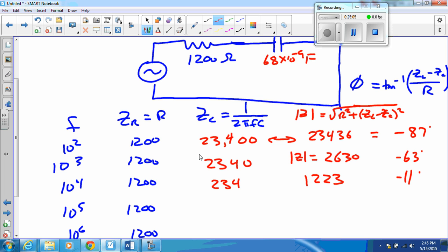Why does it do that? Because as we increase the frequency, the impedance of the capacitor goes down, down, down. And the impedance of the resistor doesn't change. Let's actually see that in the circuit over here. If I put this now on 10,000, and I compare the two, you can see the two different waves, especially if I move one of them up a little bit.